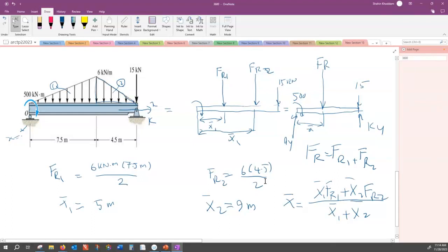So the new position is the sum of the two forces only, right? Yes, that is you substitute. This is how you add the vectors. The vectors, you add them just because they're parallel in the same direction. But then the question is, where is the line of action for this net force? This is not at x1, not at x2, this is at x bar. That x bar is found from this formula. And that formula is the integral converted to the summation.